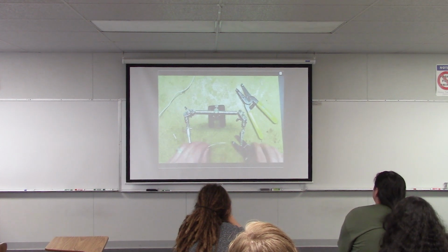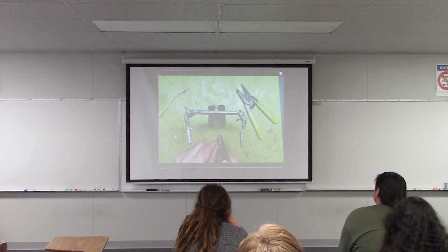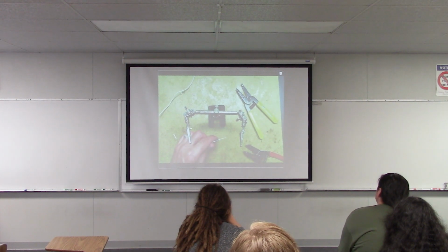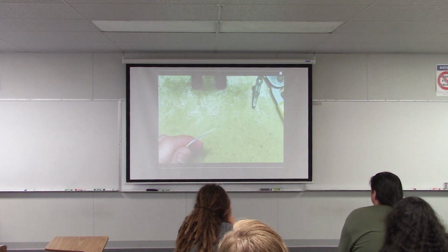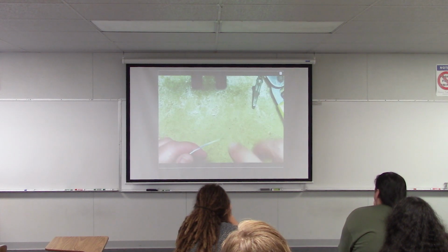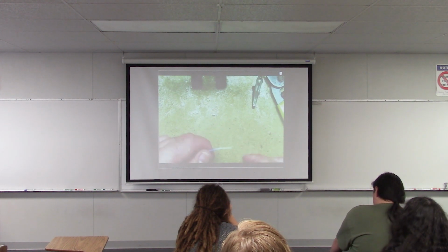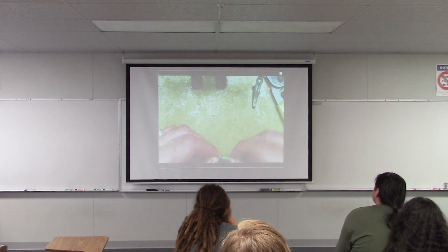All right, so you're going to do that at both ends. This type of wire is called stranded wire because if you look closely, you can see that it's got multiple strands in the middle. This makes it more flexible. When you're soldering this type of wire, you want to make sure that all of those strands stay together so that they don't end up sticking off and poking out. So the way that you can do that is just grab a hold of them and give them a little bit of a twist. Twisting them keeps them all together in one bundle.